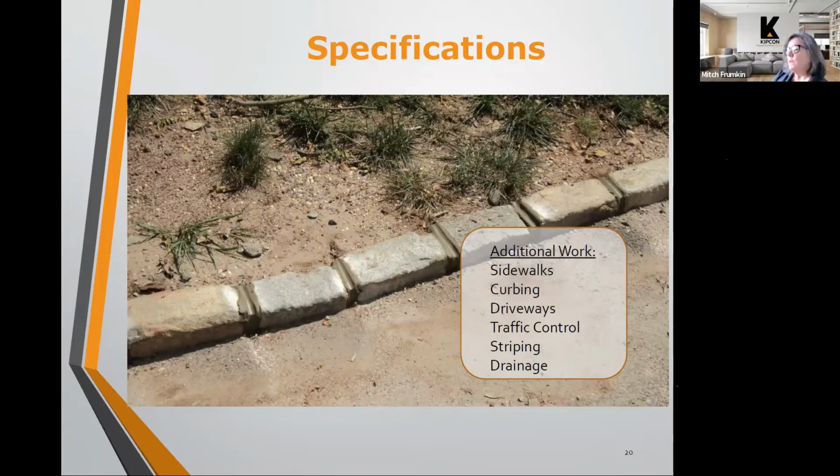If you have a very sandy soil, the two ends of the spectrum are sand and clay. Sand is very porous, and it compacts nicely, makes a nice base, and it drains well. Clay, on the other end of the spectrum, is squishy. You think of clay, it holds a lot of water. It's in some cases impervious to water, so it can create some drainage issues.